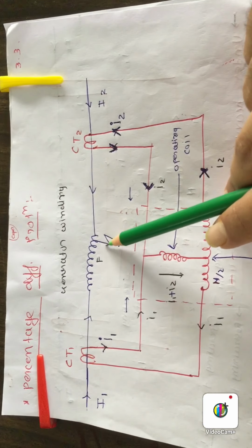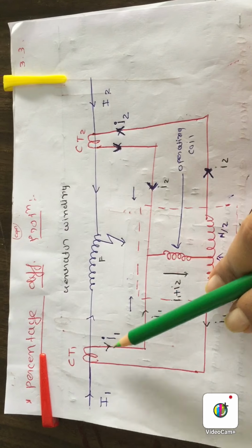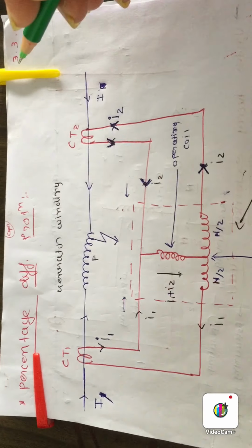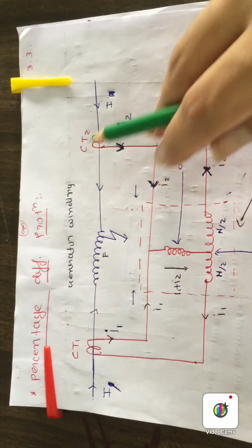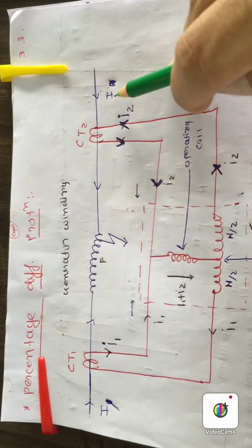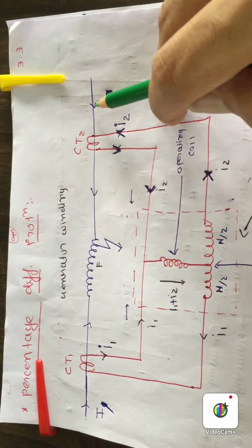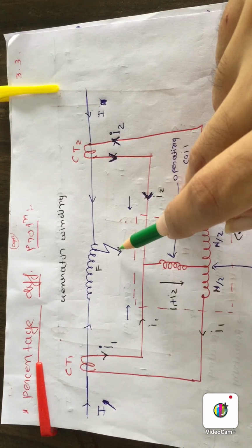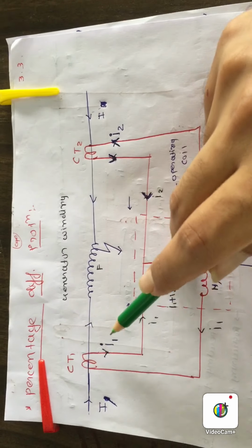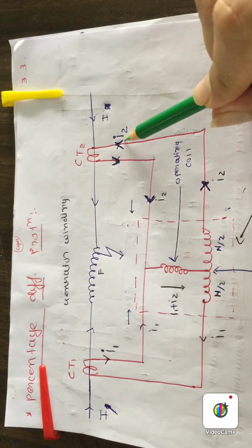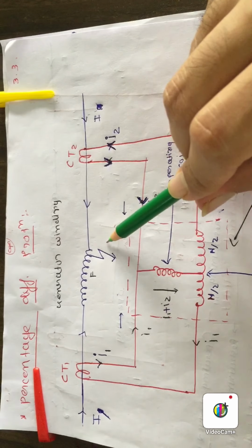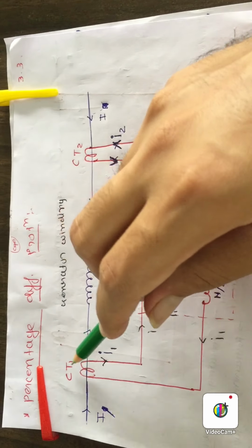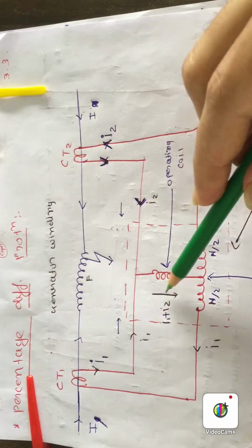You know that if a fault occurs here, then the direction of I1 is like this, the direction of I2 is like this. Okay, here the same current I flows inward, and here the direction of I is changed. Okay, it will become inward to the coil. Why? Due to the availability of the fault. Now due to this I1 will be produced, due to this I2 will be produced. But now in this condition the direction of I2 will change, so it will flow like this. The direction of I1 will be the same as earlier.